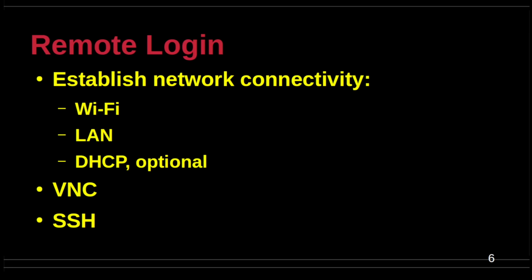The utility to connect to the Wi-Fi network is documented clearly. If you have the SSID and password, irrespective of the method you choose, the configuration is simple and does not require a reboot. Changing over to the assignment of IP addresses using a DHCP server requires disabling the manual checkbox and explicitly setting DHCP for the IP address assignment. Naturally, since the board is already configured with a static IP address, you will have to reboot the board to ensure that the DHCP assignment is active.